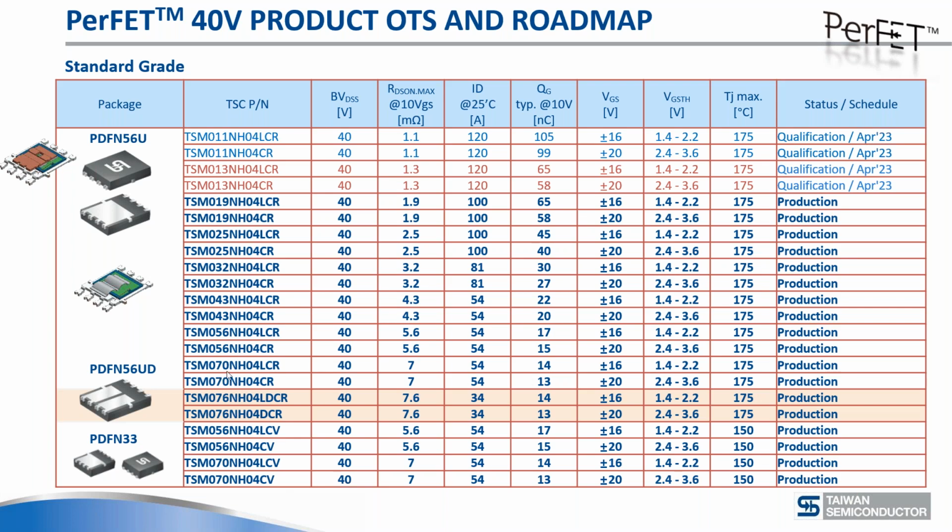On a 7 milliohm MOSFET, the difference of 0.6 milliohm is peanuts, whereas the higher metallization costs may easily offset it for us. Everybody may have a different cost calculation. That's something you need to be aware of, because you'll see that showing up much later in the presentation. So I just pointed that out: copper clip versus ribbon bonding.